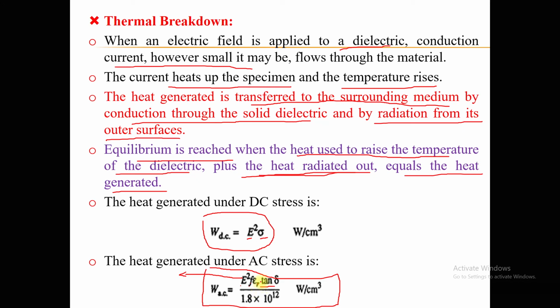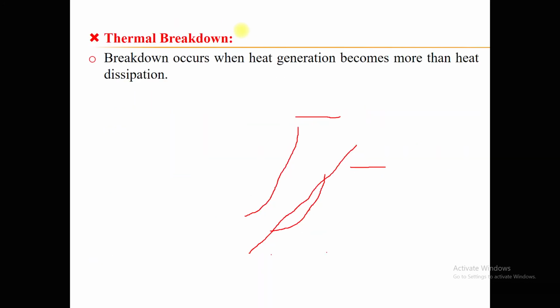As the frequency increases, the amount of heat generation also increases. So lower AC stresses can produce thermal breakdown in a solid dielectric compared with DC stress.